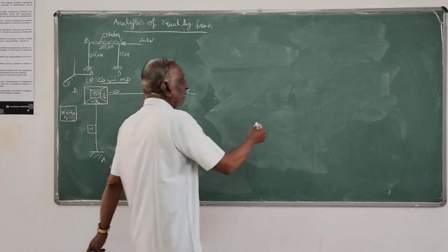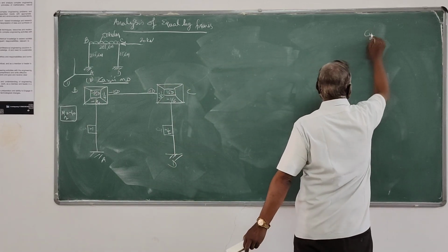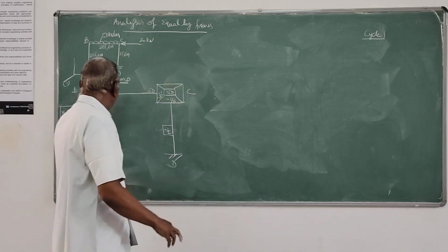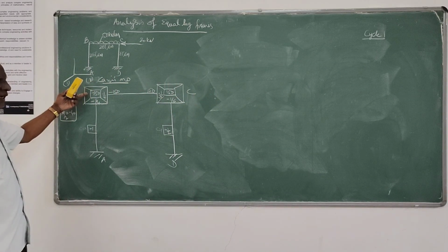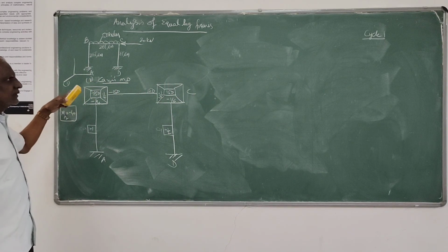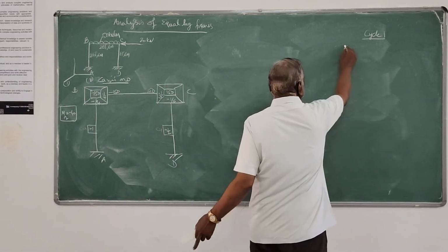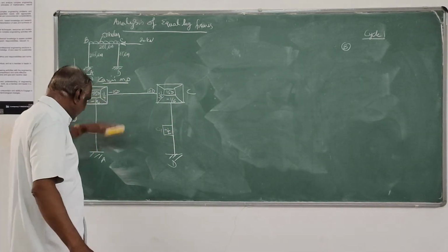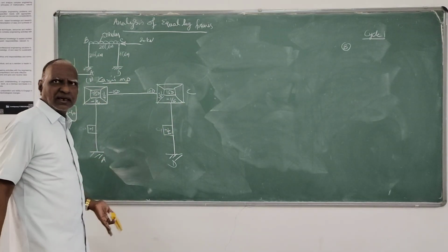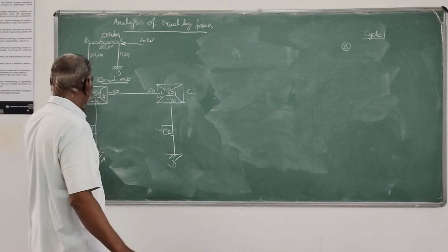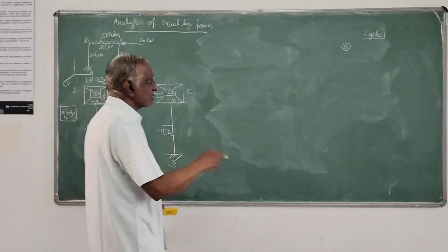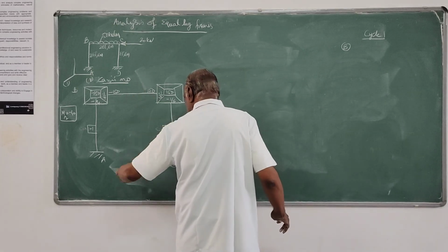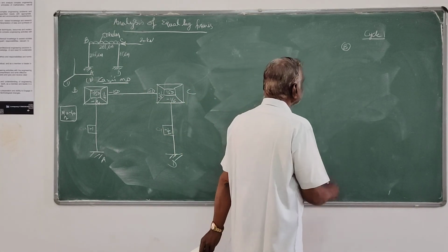So I will start on a rough scale. I will take cycle 1. I will apply the second formula. I will start from the left hand corner joint, that is joint B. Then I will move in the horizontal direction, joint by joint. Then the next story, like that I will move. First you start with joint B. So in that formula, the first thing is the rotation factor. I will leave it. First I will determine the rotation contributions at each of the joints.